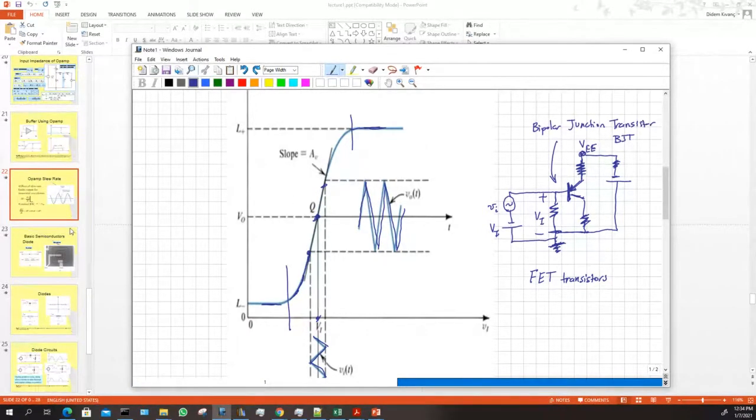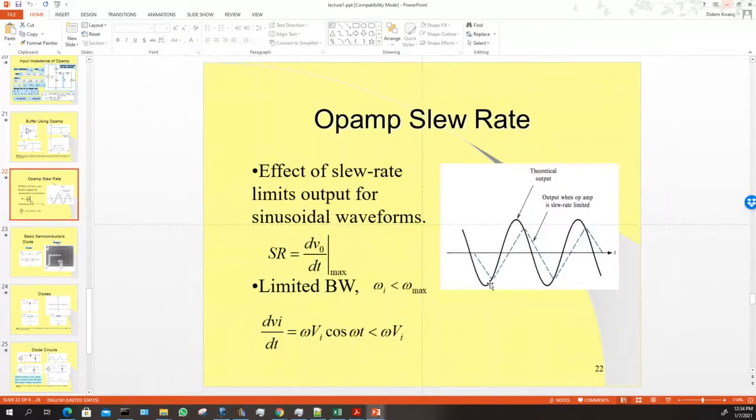But the system takes a little while to change, to adapt. And you can't show that on this figure. There's no time on this figure. I mean, there is time on it, but the input-output curve is not set to show time. In reality, it takes a little while for this circuit to adjust, for the voltages to change on the capacitors. It depends on the resistors that you tie as well. Large resistances generally mean a slowly adapting circuit.